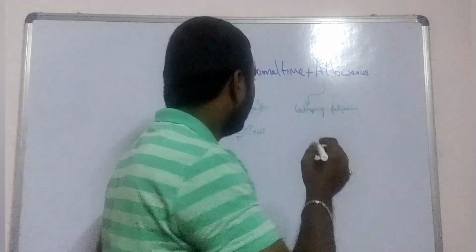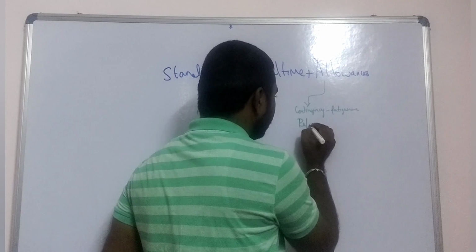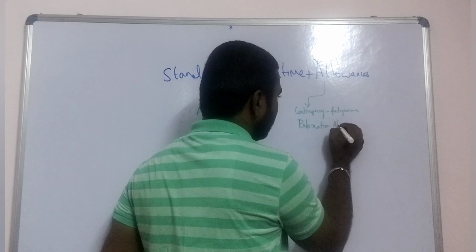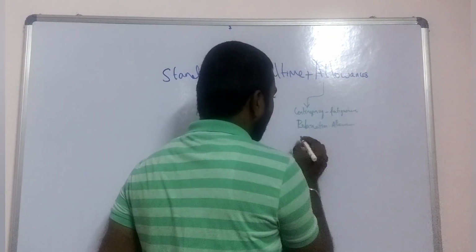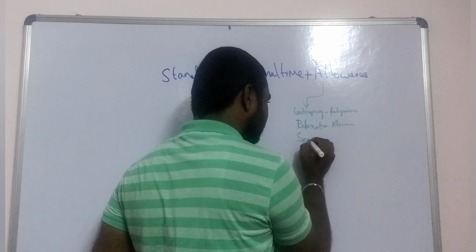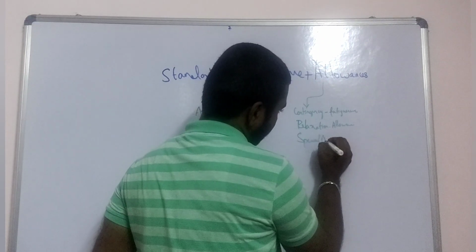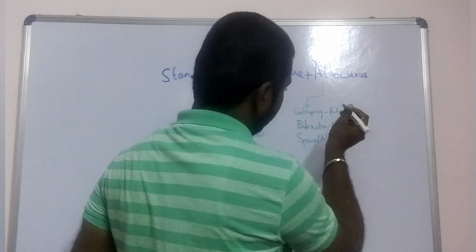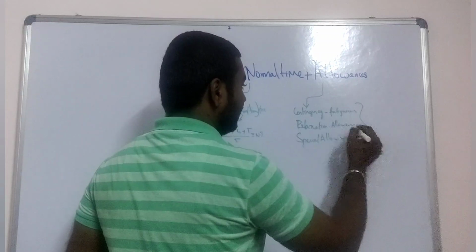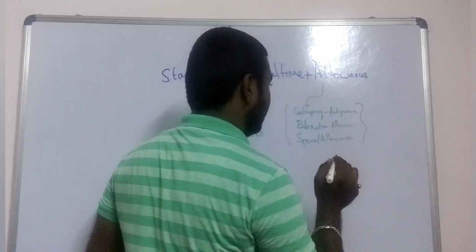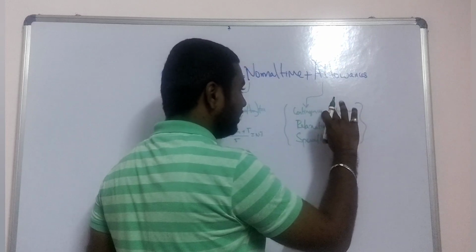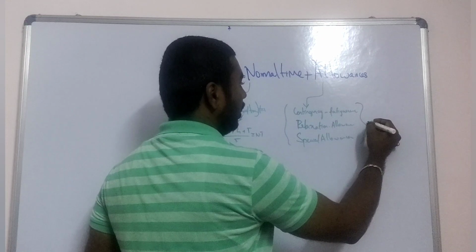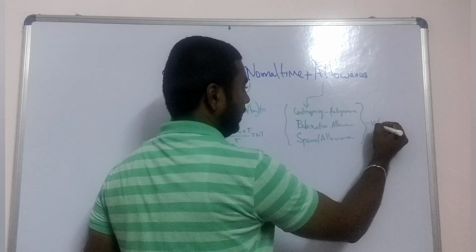Secondly, there is relaxation allowance, and the third one is special allowance, which covers an unfortunate or unexpected happening or attending nature's call. These three major allowances are considered in standard time calculation, and they are made deterministic by awarding a percentage value that is decided by the organization.